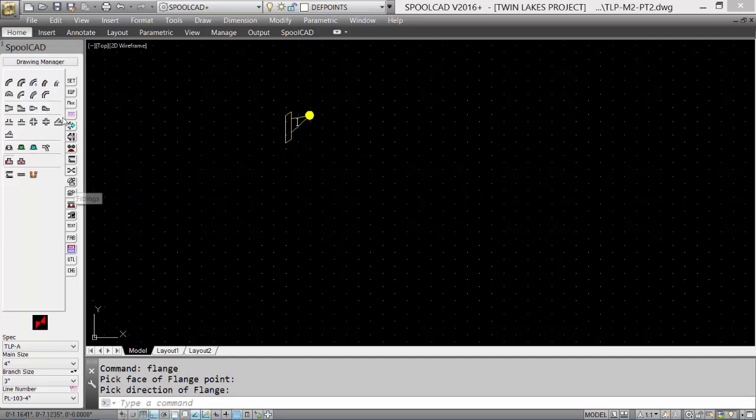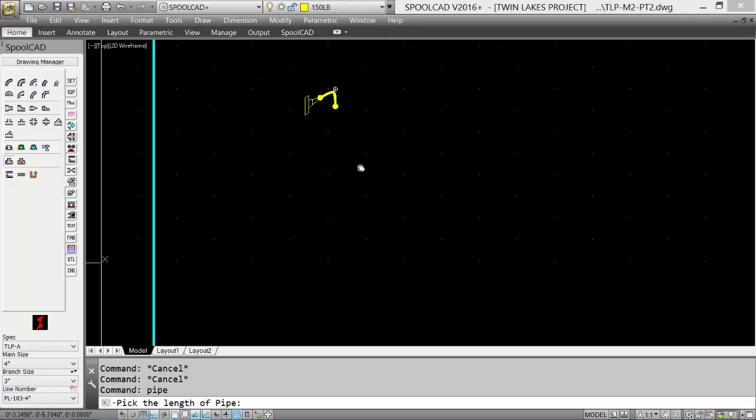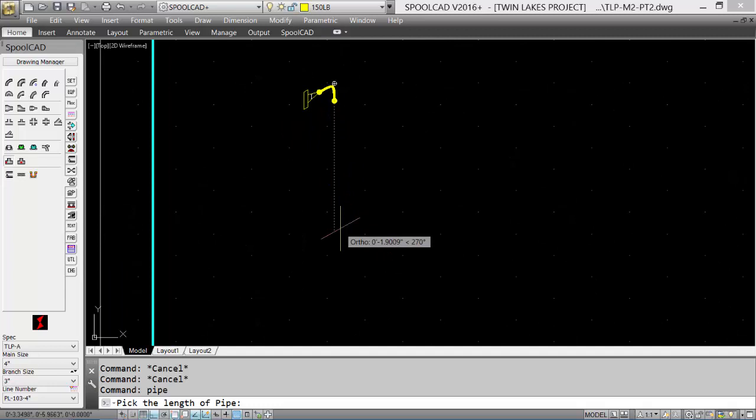Now we'll select our fittings tab, select our elbow, and automatically it only asks now for the side of the elbow. So now we can just pick down and it automatically picked the direction along the autoroute plane. Now I can add a piece of pipe. And I'm just now picking just the random length. So the start point was automated to the end of the elbow.